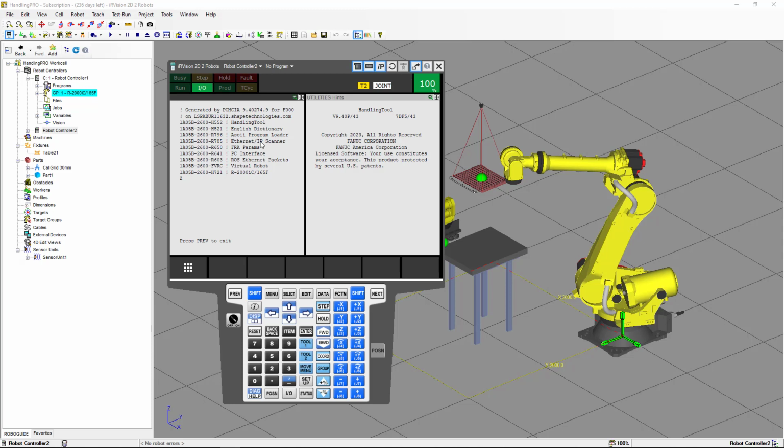Robot 1 is going to be the robot master, and robot 2 is going to be the slave. So for the robot slave, I believe we don't need to have the Ethernet IP scanner, only the Ethernet IP adapter will be enough. That's something you will have to double check. But in this case, I selected the Ethernet IP scanner, just in case we have a communication with the PLC.